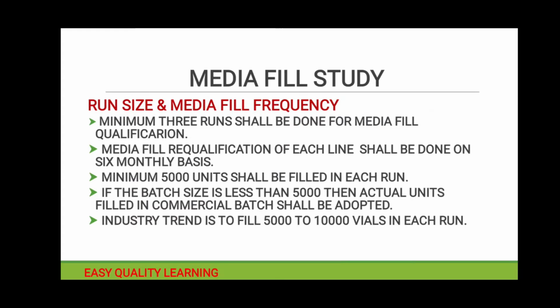Then run size and media fill frequency. A minimum of 3 runs shall be done for a media fill qualification. Media fill requalification on each line shall be done on a 6 monthly basis, so every 6 months we need to do a qualification of each line. A minimum of 5,000 units shall be filled in each run, and if the batch size is less than 5,000 units, then the actual batch size needs to be adopted for our media fill trials.